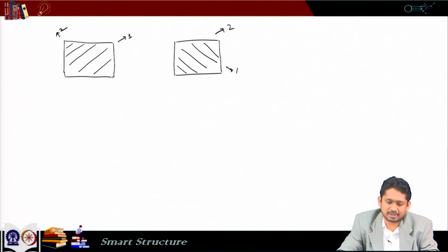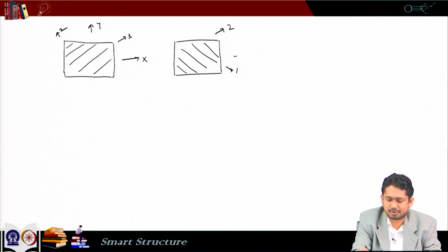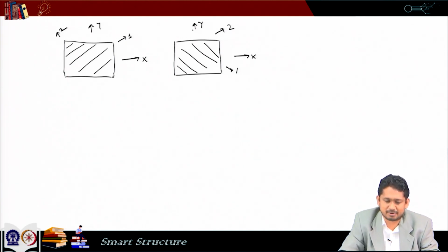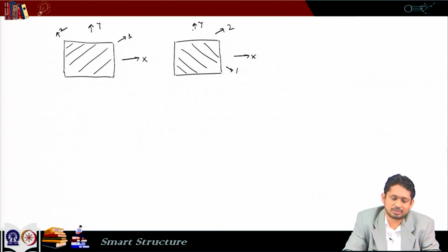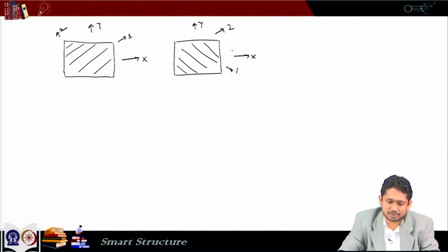So when we want to analyze a laminate, we need to define a global coordinate system, and better that with respect to that global system we define our properties. So suppose I have a laminate which is made of these plies, we define a system like this, x y, which remains the same for all the plies, so it is global for the entire laminate, and we define our constitutive law with respect to this x y system. Then we can analyze the laminate. So that will be our today's job.